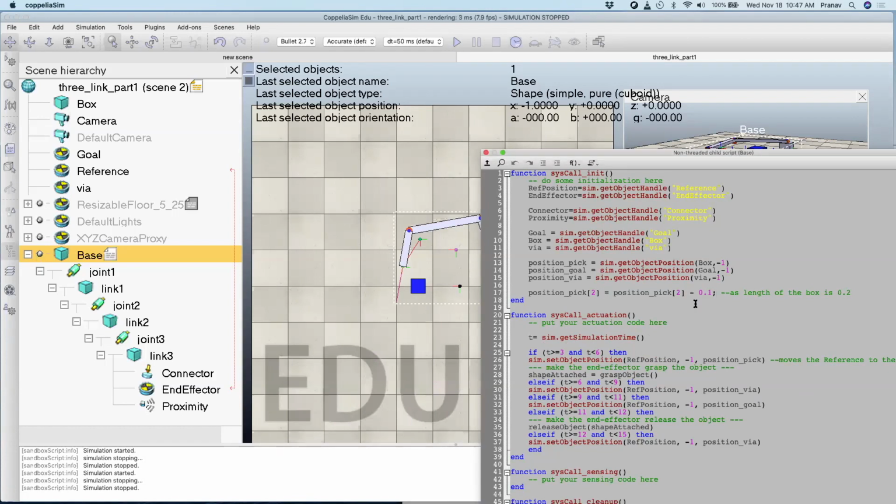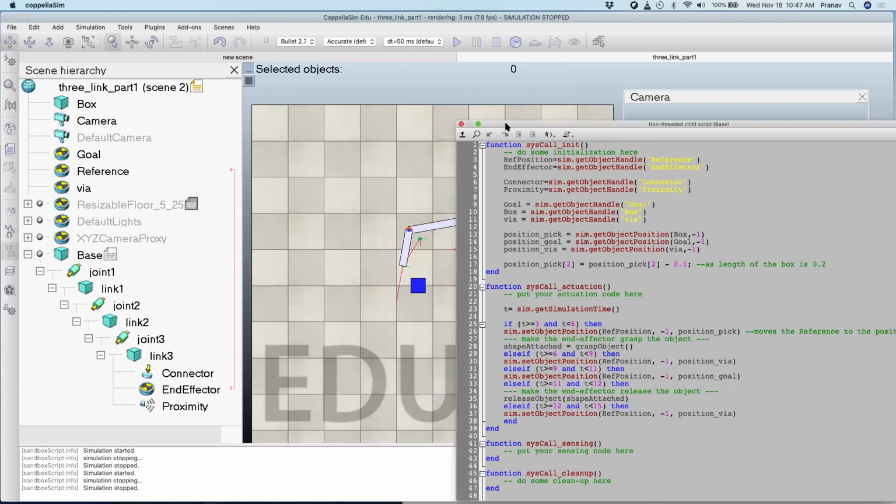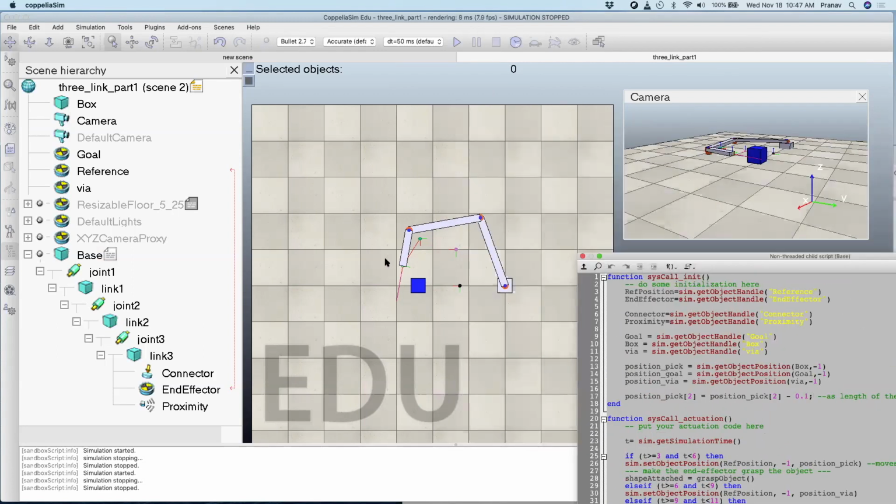In that case, what you would need to do is have a homing action. In robotics, homing is when you are trying to get to something, you go close to it fast, but maintain a certain distance, and then you go slowly to see that it's actually there. So you'll have the end effector here, and then slowly start going down with the proximity sensor, and you'll keep detecting the box and seeing if the box is visible or not. At some point, when you know the box is close enough, that's when you'll attach.